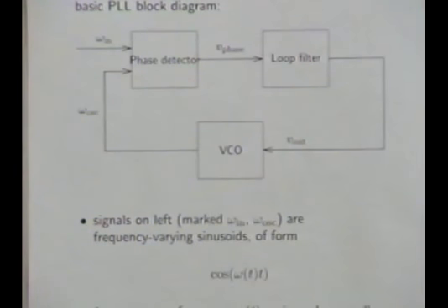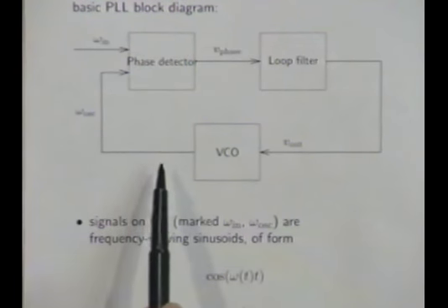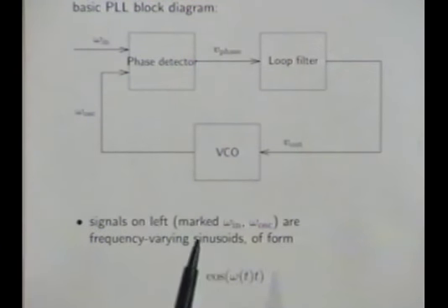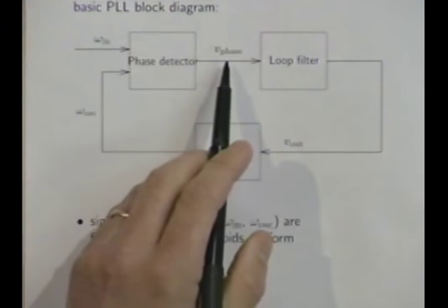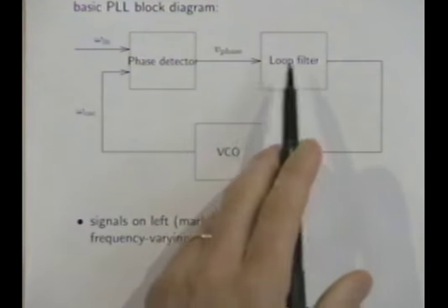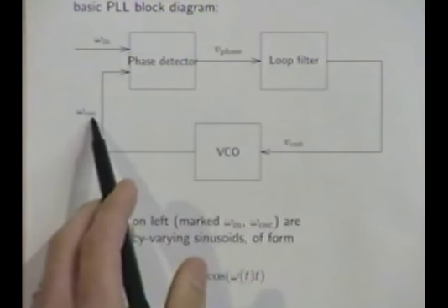And there's lots of ways to make VCOs. So for example, using the RC one is a very common way to make a VCO. And the capacitors are actually active devices, and by changing the bias voltage, you change the capacitance, and that sweeps the frequency. So that's one way to make a VCO, but there's lots. Okay, so this is the idea, and the idea here is, if you build this right, you have feedback. And what happens is, if these two guys here are transmitting, if they're phase locked, in other words, if the frequencies are equal, the phase is some constant number here, and this voltage is constant, and this thing is matched to that.